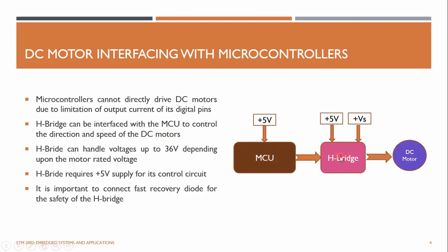So basically, we can use an H-bridge driver. Its job is to get the control signal from the MCU, because it can accept any control signal, but generate a current from 1 amp or any other amps related to this motor, based on the capability of the H-bridge. So accepting any digital signals, pulses from the microcontroller.